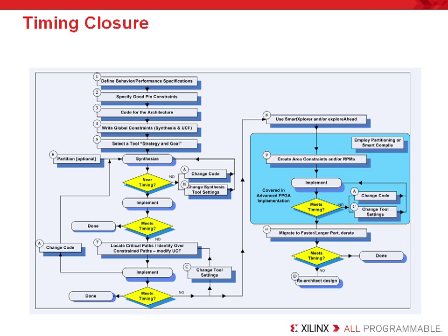What I want to point out to you is that the most important efforts to improve design speed are recommended very early in the design flow, even before completing a single implementation of the design with the place and route tools. And this is where we make good coding decisions, and this explains why making good HDL code is critical and is most beneficial when good coding styles are used from the beginning of the design process.